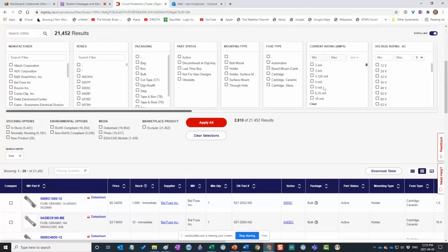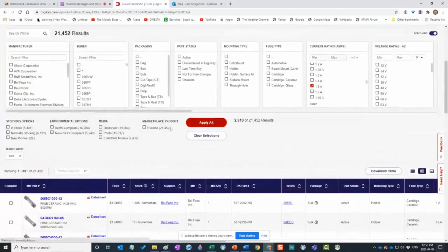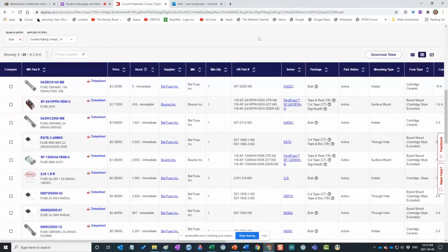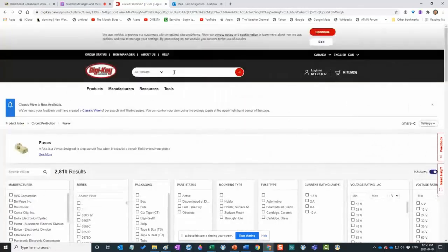So when you're selecting fuses, you can look at this, and if I just look through here, you can actually go get a part number for this particular fuse. So apply the filters, 1.5 amp, whatever. You can get a part number for this, and you can indicate that this is the best one to get. And you can say the manufacturer's part number. I'll talk about the manufacturer's part number in a second. I'm going to put selector switch.